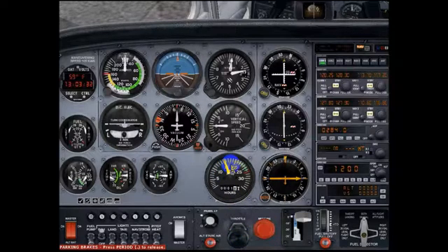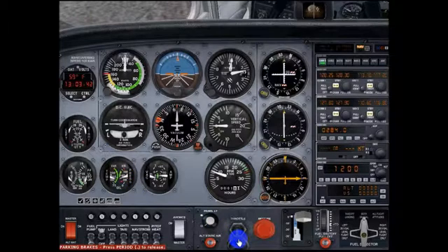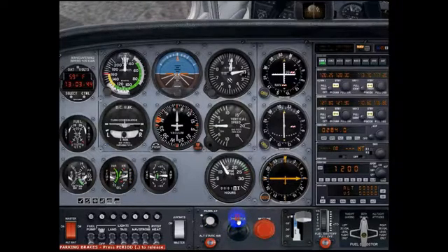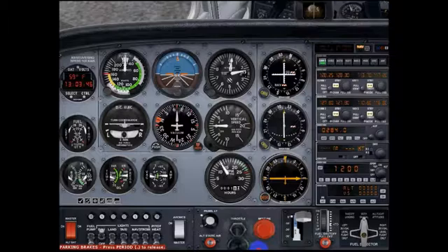we'll see that the tachometer, or revolutions per minute, of the propeller is increasing, and the pressure also built up. Okay, so we can see that. We typically idle at 1,000 RPM, so we'll gently push the throttle a little bit, so it idles at 1,000.